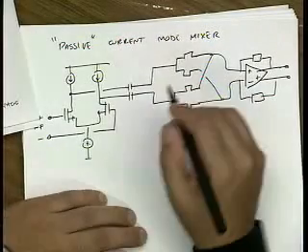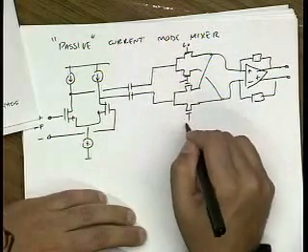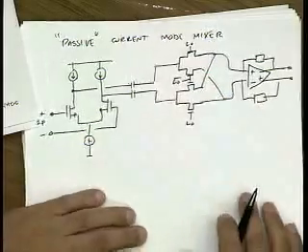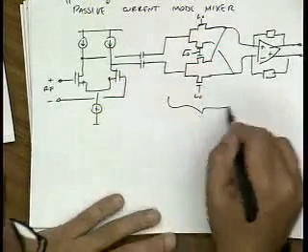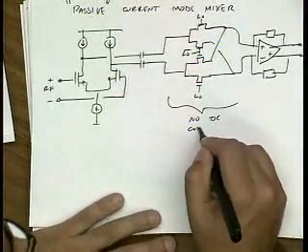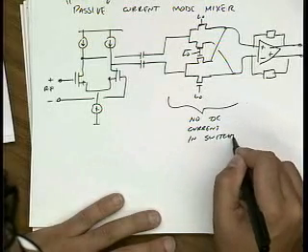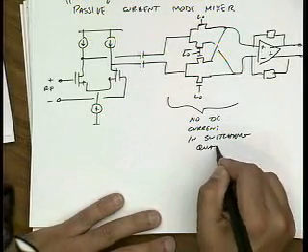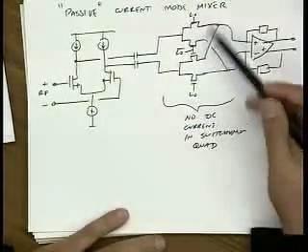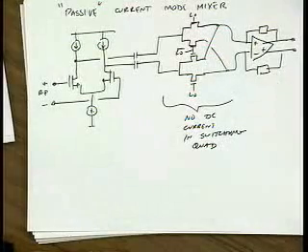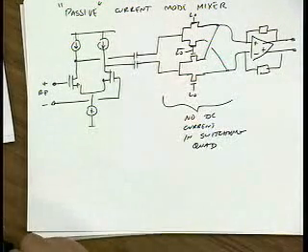So this is what the full circuit looks like. So let me drive these ports with LO and these ports with LO bar. So the idea of this mixer is there's no DC current in the switching quad. So very similar to the voltage switching mixer, I just turn these devices on and off. They go into triode, they go into cutoff. Okay? And there's no net DC current flowing in here.